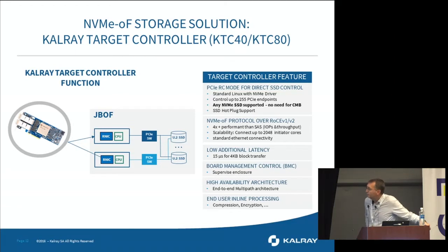If you want an overview of what we propose, in fact, this is a target controller. The target controller is basically an RDMA NIC. But instead of using the network processor on these boards as a PCI Express endpoint, we are using this processor in a root complex mode. Meaning now you can combine the function of the RDMA NIC and the CPU. Having the root complex, you can do the SSD enumeration. As we can have a standard Linux with a standard NVMe driver directly executed on this MPPA processor, we can control the SSDs directly from the RDMA NIC.